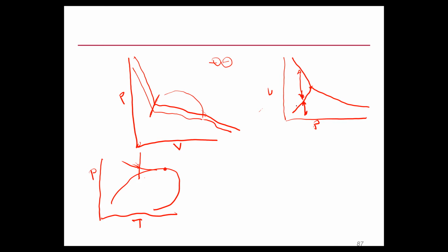The oil will shrink, and as it shrinks the asphaltene problem is reduced. Here we don't have any asphaltene problem. That's the shape of the asphaltene phase envelope. So depletion can result in asphaltene formation.